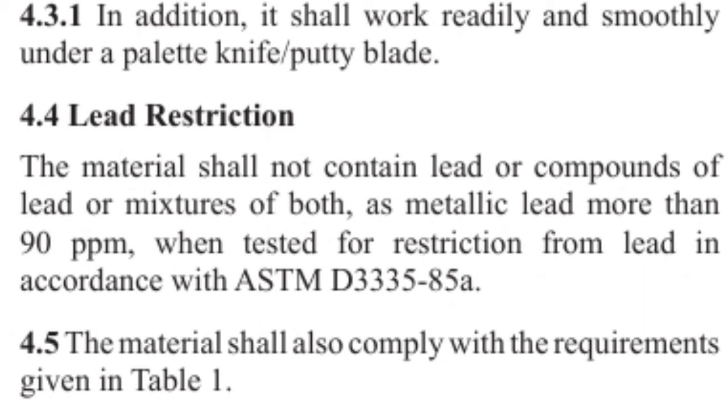Now why? Because this is an interior item, used where people will stay. If the lead percentage is more, what will happen? It becomes a health hazard, and it will not be advisable for the habitat using it, and they may feel uncomfortable, like irritation, sneezing, and allergies. That can be possible. So the IGBC has given this guideline that the lead percentage should not be more than 90 ppm. Whenever you are selecting the wall putty, you need to check that quality parameter also, because it is very important.